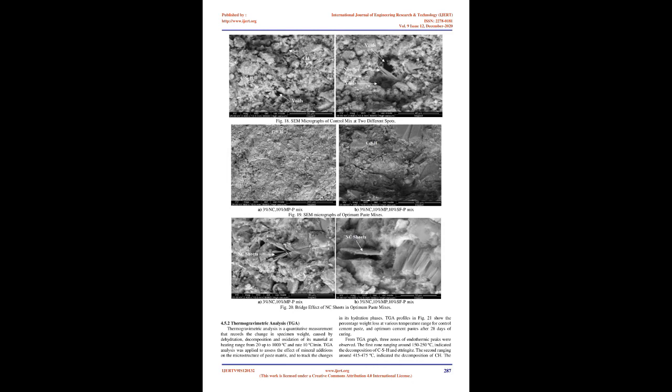4.5 Microstructure Analysis. 4.5.1 Scanning Electron Microscope Analysis, SEM. SEM analysis was applied to assess the performance of mineral additions in the cement microstructure. SEM micrographs in Fig 18 to 20 show scans of the control cement paste, and pastes contain optimum ratios of NC and MP after 28 days of curing. SEM analyses were compatible with the mechanical properties previously discussed. For instance, weaker performance in mechanical properties was noticed for control mixes in comparison to optimum strength mixes.